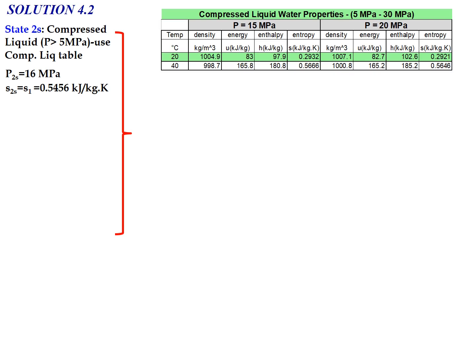However, in this table we don't have a direct value in terms of enthalpy, entropy for 16 megapascal. So now what we have to do, because data is not available for 16 megapascal, we need to create the table for 16 megapascal.